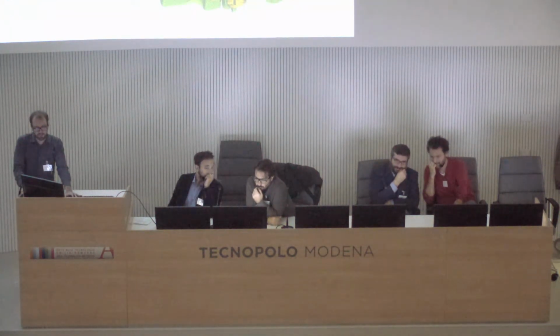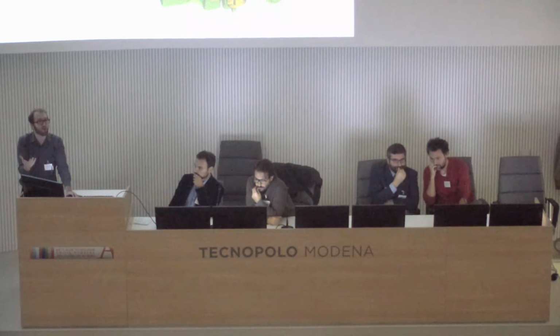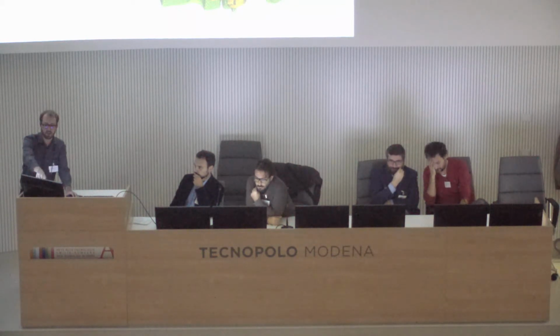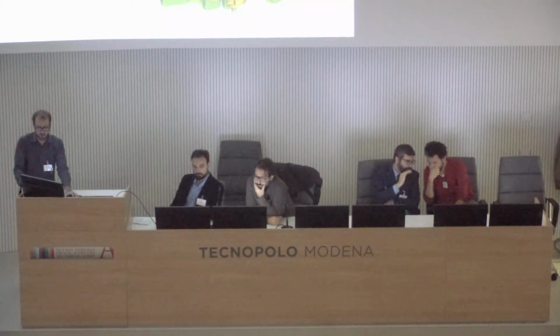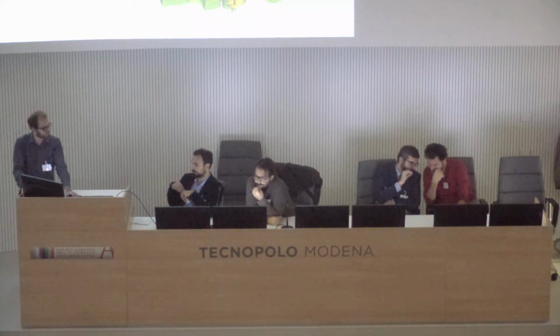And then from that we managed to do a sane mesh. When I say a sane mesh, at the end we will do a fatigue analysis, so there will be a crack inside of our mesh. Here we first started with a sane mesh, and we managed to have very, very small elements around where there will be a crack, so we know we can capture what happens over there. As you can see, it's a very complicated mesh, around 600,000 nodes. It's in 3D, so we're close to 2 million degrees of freedom for that problem.